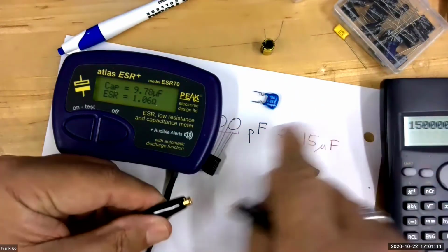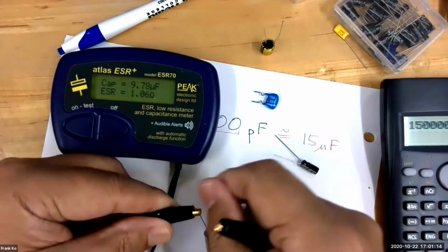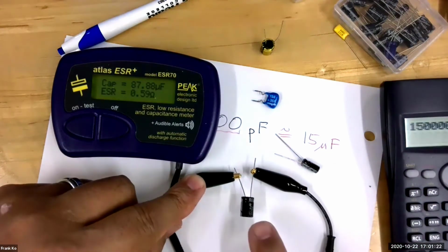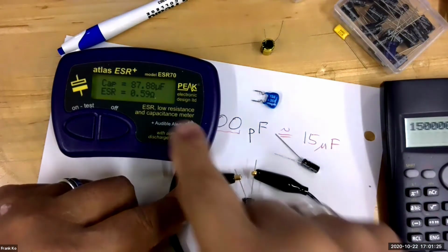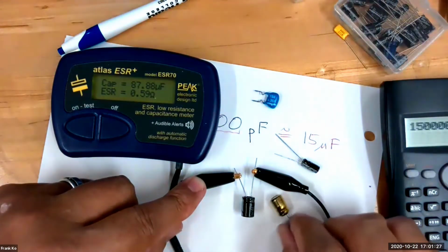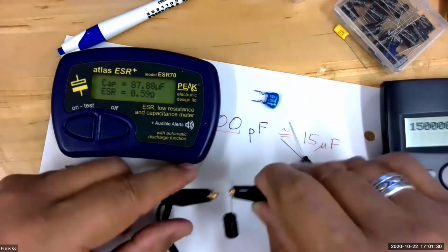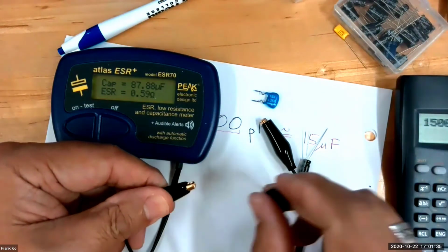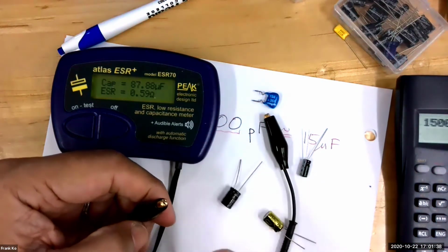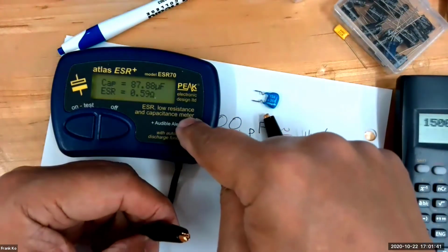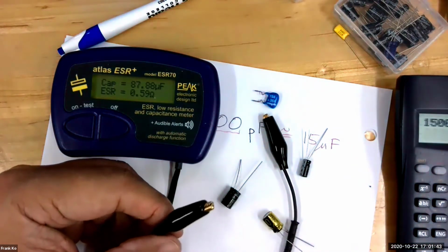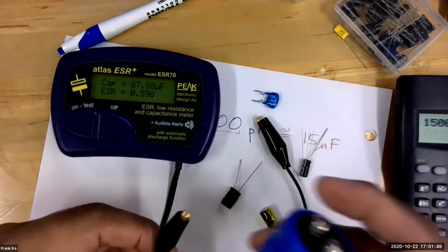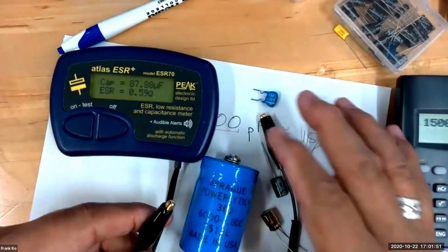Now, let's go ahead and check this particular guy. This is a 100 microfarad cap. Yeah, this one's pretty far off. It's supposed to be 180, just like this. So we're not going to rely on these 100 microfarads very much for our experiments. When we get into AC circuits and the value of the capacitor is critical, we want to use a capacitance meter to double check the cap value so that we can make sure our quantities are correct.